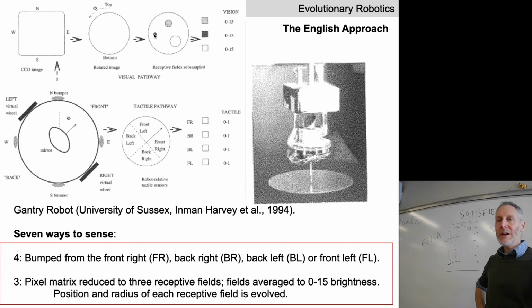For every image arriving from the camera, they take all of the pixels inside each of the 3 fovea and take the average brightness, the average whiteness of the pixels inside that fovea. So this fovea is picking up some dark object here in the 360-degree view. This fovea is picking up intermittent brightness somewhere else in its view, and bright colors or brightness somewhere else in its field of view. We have 3 fovea.